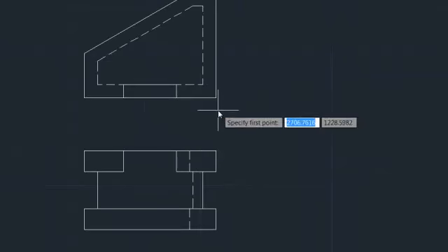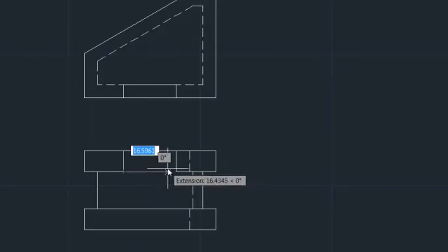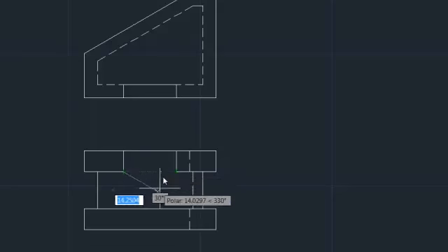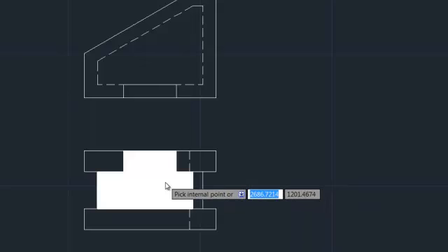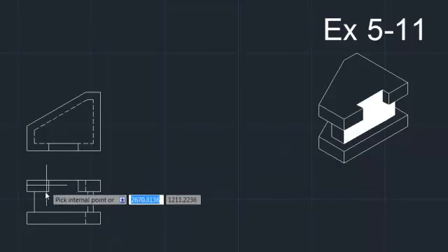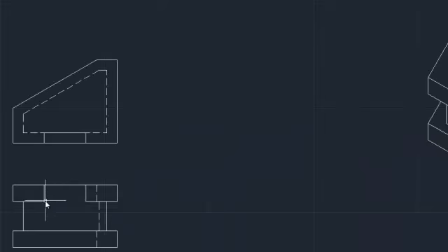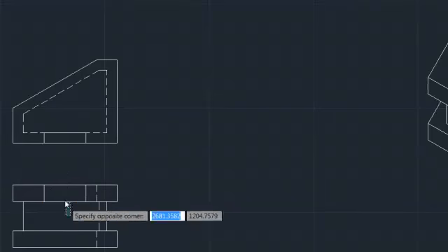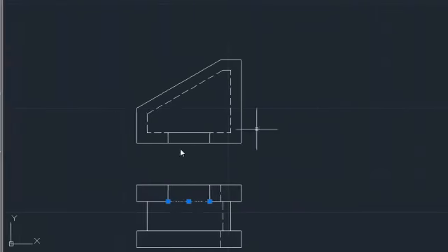So that's that. Now, as well, if you look from this front view, this gap here, you won't see anything in terms of what's actually there. This is all one face. That's all one face in there, just like it would be shown over there. But you would see the dotted line along that back line. So we will have a hidden line in here. Drop that one down as well.